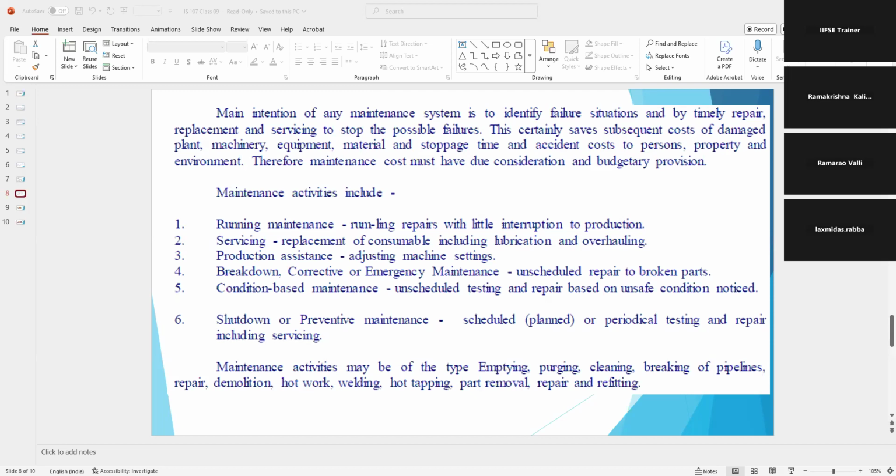From now you are not supposed to do that. No, but sir, if in running condition you want to do any activity, the permission is given by management. You take the interlock bypass to the system, then you can do it. Yeah, I know some of the situations are not in our control, but always we can find the right solution. But even if it is bypassed, immediately you have to make them active.